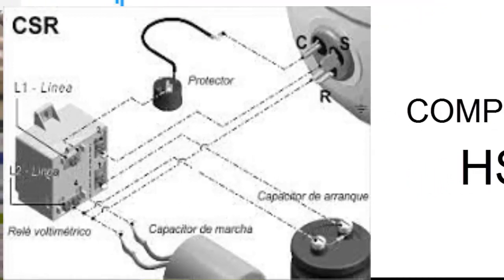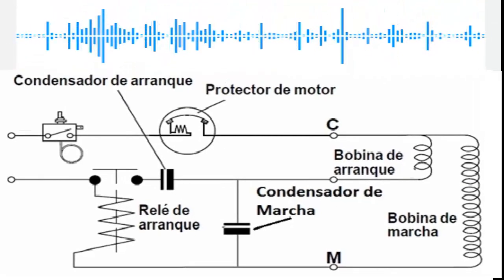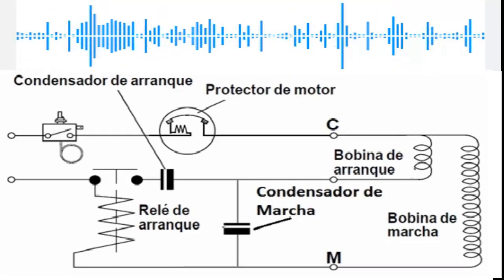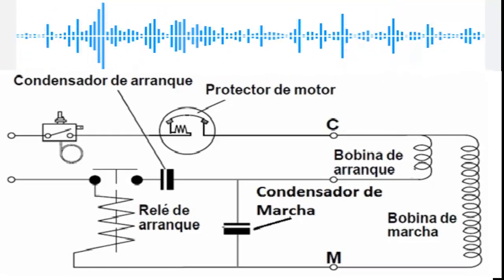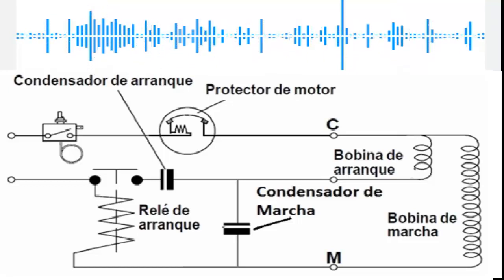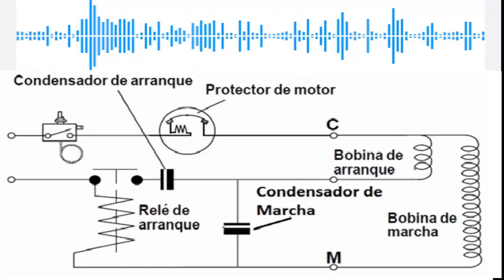The voltage in the start coil increases as the motor compressor's speed rises until it reaches a specific value. At this point, the relay's armature is attracted, opening its contacts and disconnecting the start capacitor from the circuit. After the opening, there's induced voltage in the start coil sufficient to keep attracting the armature and keep the relay contacts open.